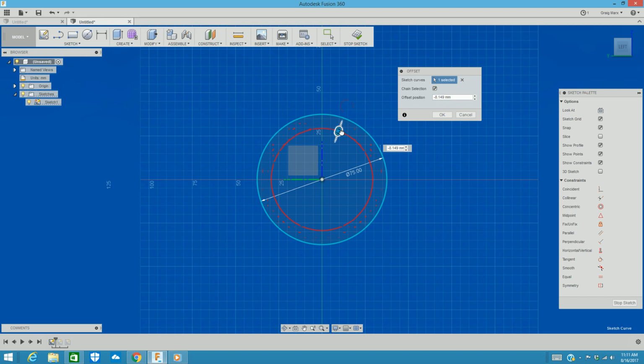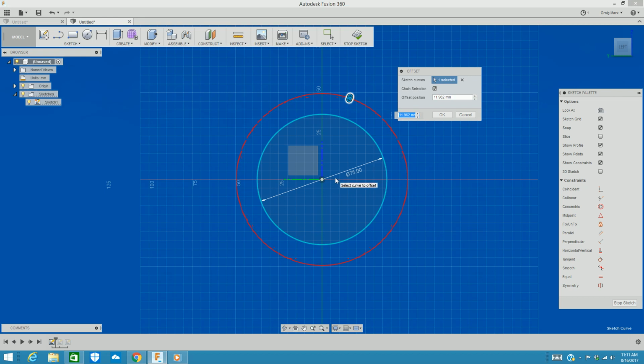So let's say I wanted my circle. And if you remember, I think the first time we did two circles, one was 100. So if I wanted this to be offset and I wanted it to be 100, some people right now are thinking, oh, you should make that offset 25 millimeters. That's incorrect, because it would put 25 millimeters between this line and this line, and also between this line and this line. So it would be like adding 50 millimeters to the circle. So in this case, you want to think about it more like radius and less like diameter.